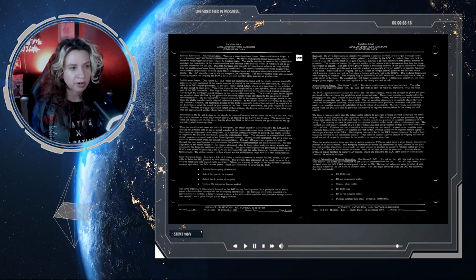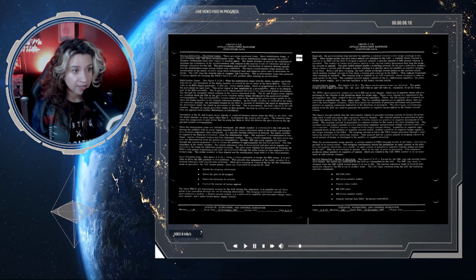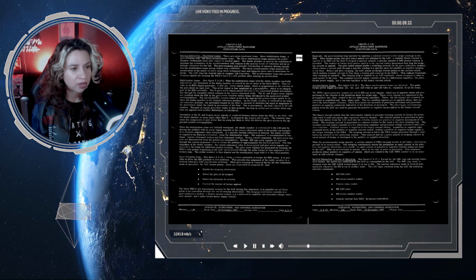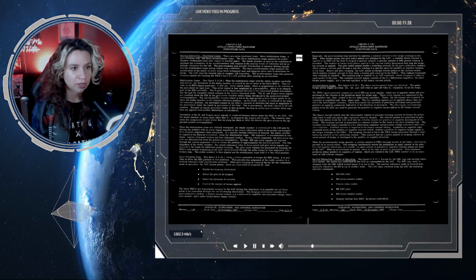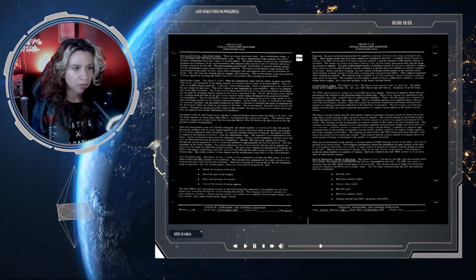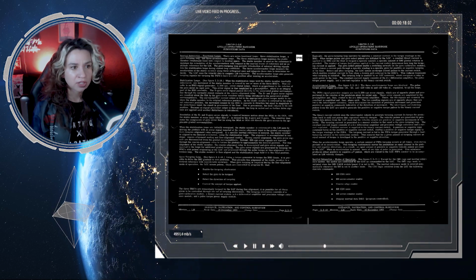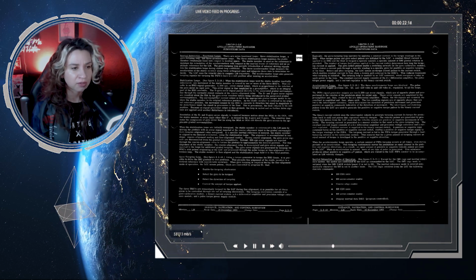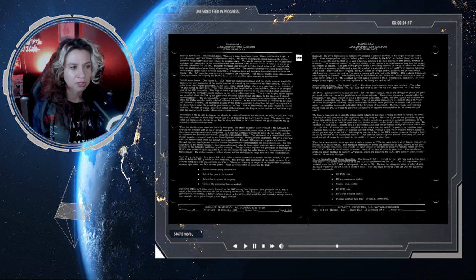The torquing current is fed to the PIPA's torque generator through a load balancing network in the calibration module. This ensures that for a given amount of torquing current, an equal amount of torque is developed in the positive or negative direction.